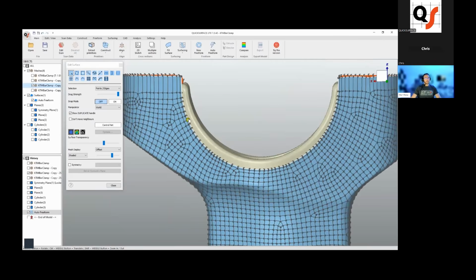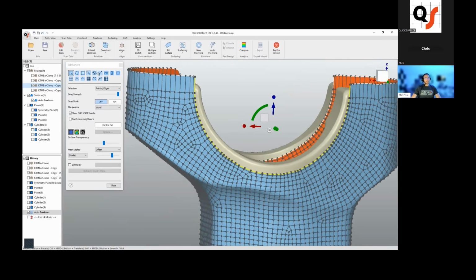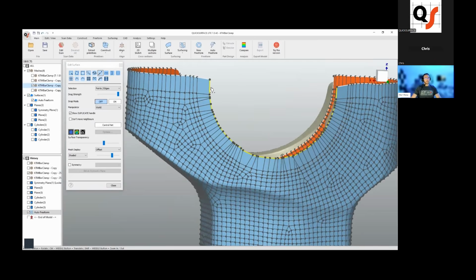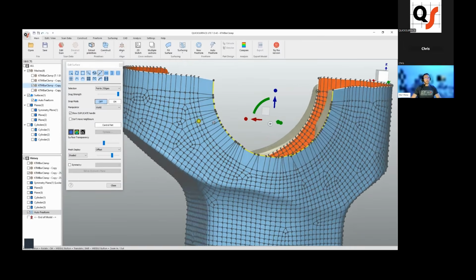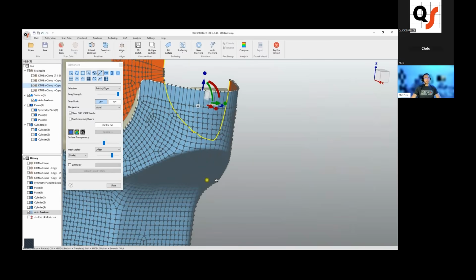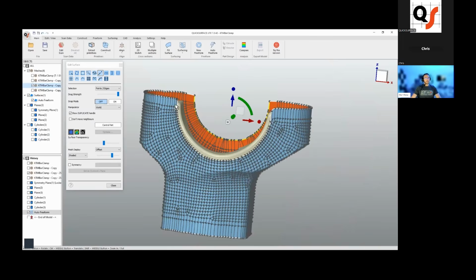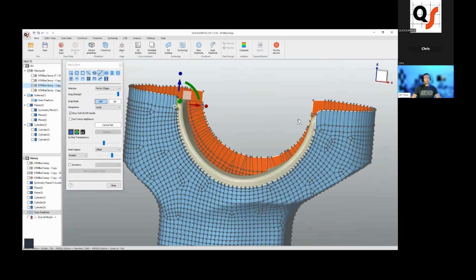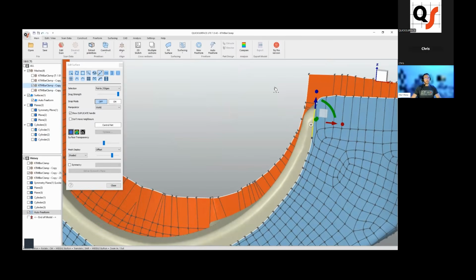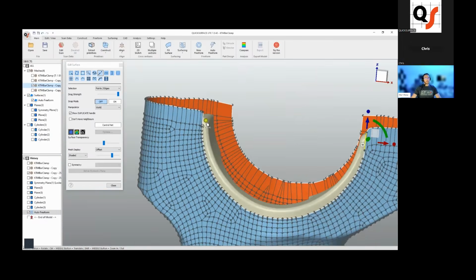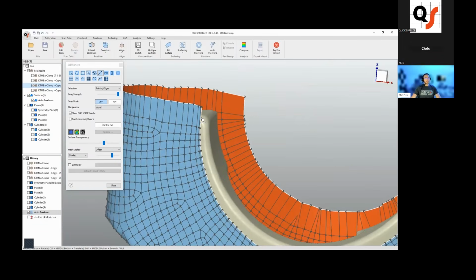All right, so now for this area here, if I double click this, what we want to use is this tool called Extrapolate. And what Extrapolate allows us to do is extend this inward, basically in a tangent direction from where it is. We're going to have to come back and do a little bit of cleanup on that, which we'll do in just a second. But I want to repeat that over here. So again, double click. And you have to be careful again because it looks like it's rolling over this edge. So I'm going to select there, hold down Control and double click.